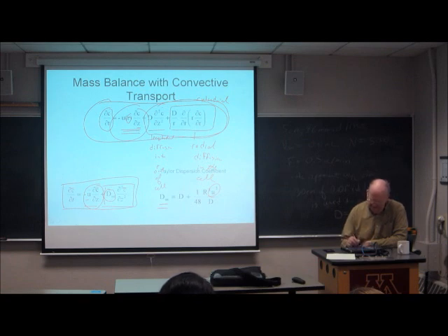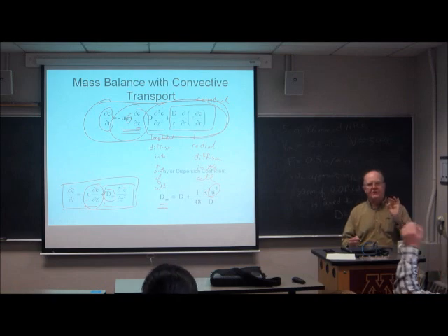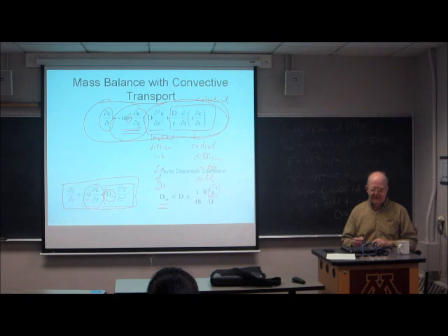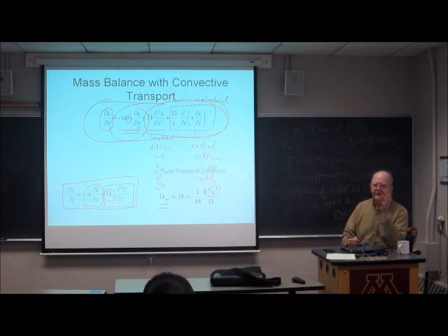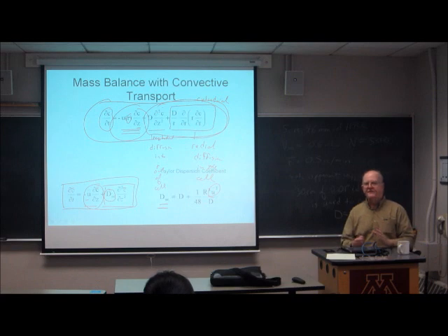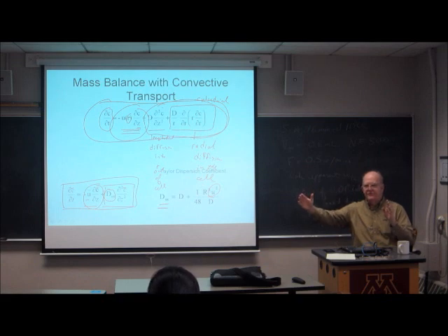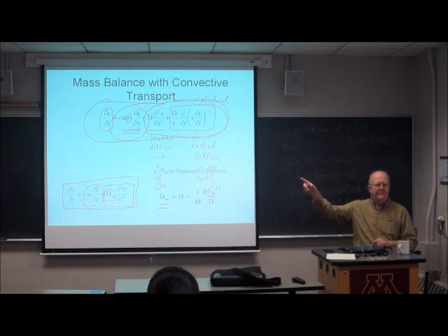So this now is the dispersion coefficient that we're going to use in this equation. And this equation can be solved. And it turns out that it's not at all hard to solve. And it turns out that it predicts that the peak will be Gaussian. It predicts the time it will take to transport the peak through the tube, and it predicts the sigma squared of the peak when it comes out the end of the tube.